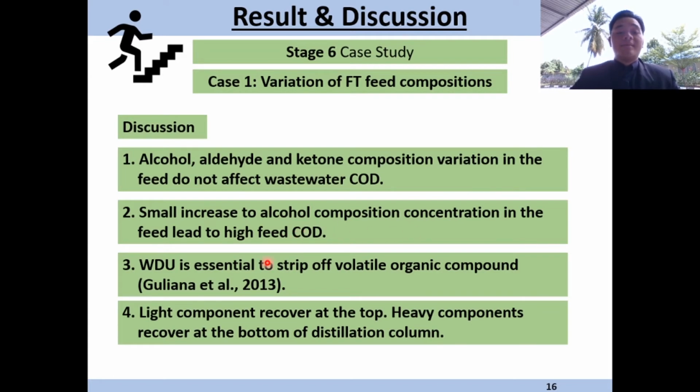As such, the water distillation unit is essential to strip off volatile organic compounds, which means that the light component is recovered at the top and the heavy component is recovered at the bottom of the distillation column, which will determine the COD of the stream.